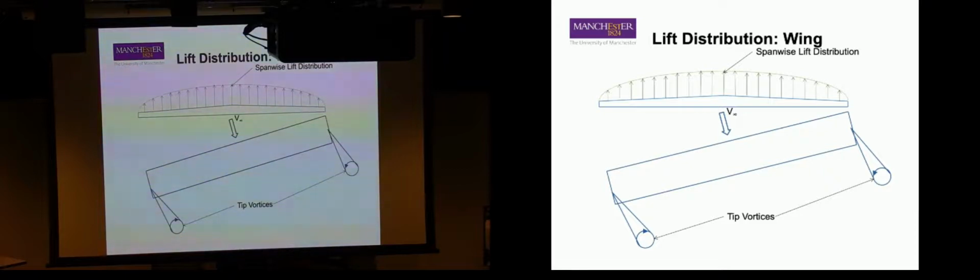It's not a great distance. They are literally like this. That step change is called a shock. So unless I have a shock wave, that pressure differential has to go to 0. Now, the only time we can have a shock wave is where we have supersonic flow. You don't get supersonic flow differential, as in greater than Mach 1 speed difference between the upper and lower surface of the wing at the tip, unless you theoretically are flying faster. So what happens is flow will move from the lower surface to the upper surface, generating our tip vortices and canceling out that pressure differential. Without that pressure differential, we can't have lift at the tip. So it goes to 0.